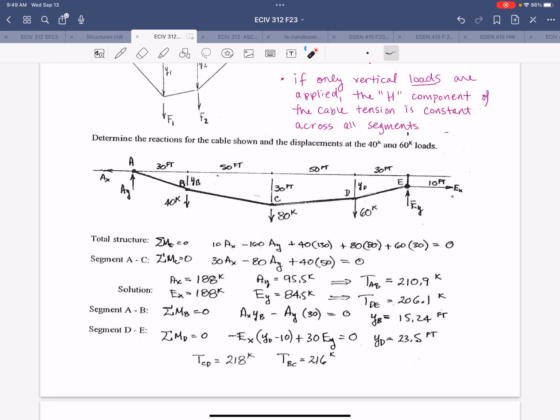So those ties would be tension only. So you can just kind of gauge by looking at the configuration and understanding how the load is coming in, right? So it would be a gravity load on the top chord. You can intuitively or just qualitatively assess how those forces are going to flow through the truss, right? What is the load path of the truss?